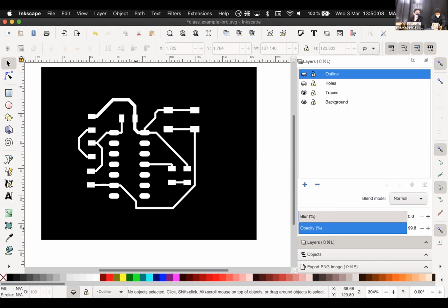Okay, so for academy students, today with Neil, we're going to see the assignment. This week's assignment is to create what we call a hello board. That is just a board with a microcontroller, an LED, and a button. On the academy webpage, in the schedule, you have hello boards for the different microcontrollers we can use: ATtiny, ESP32, whatever. So we'll need to decide which one you want to use and create that board.